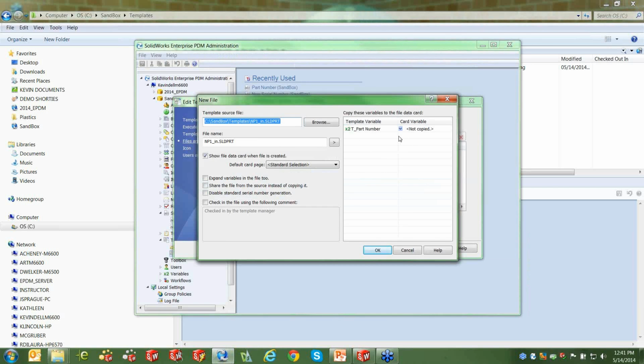Okay, so now this brings up a whole other screen that we haven't seen before. First of all, it's asking where the original file was, and it captured the path. That's fine. Then it's asking me what I want the file to be named when it's completed. And we're going to just change the name here, and this is exactly how we rename the folders. We go %T underscore part number. We're copying this off the clipboard, %. So we're going to use that part number to rename it.